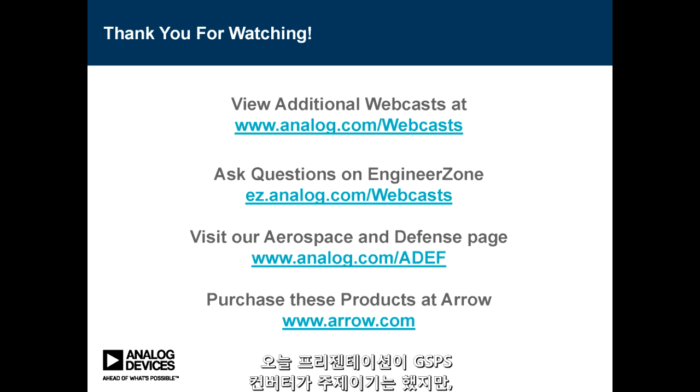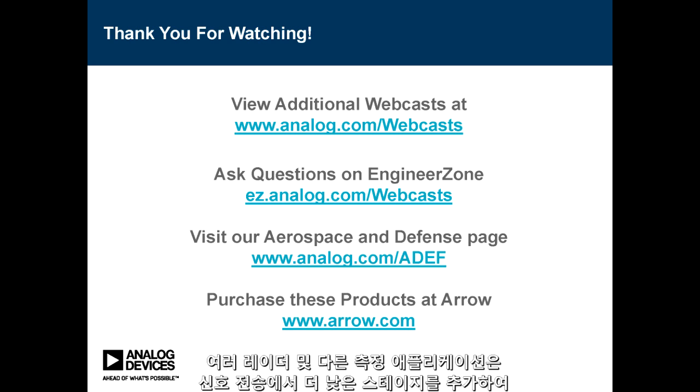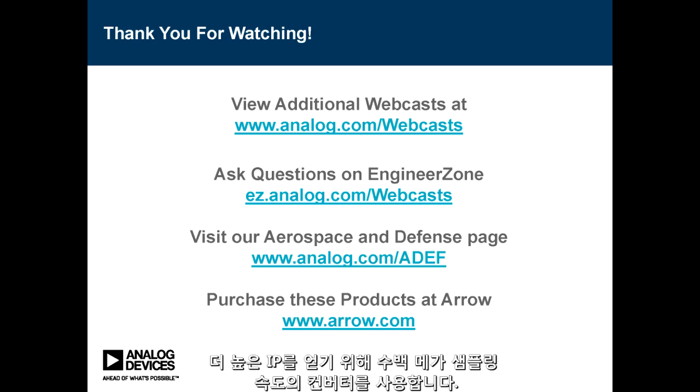Well, keep in mind that even though in this presentation we covered gigasample per second converters, not all applications require one. Many radar and other instrumentation applications use converters in the hundreds of megasamples per second to capture higher IF, with the addition of more down stages in the signal chain.